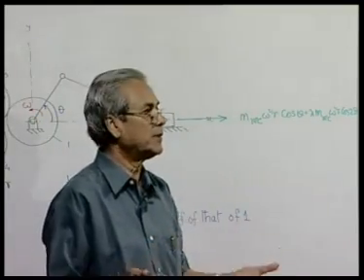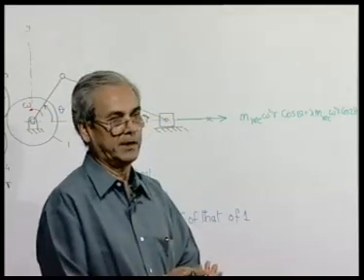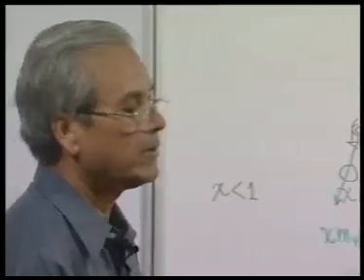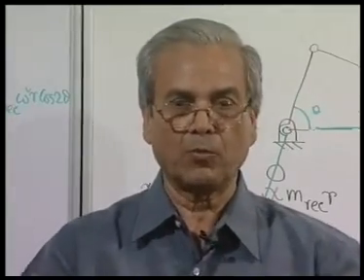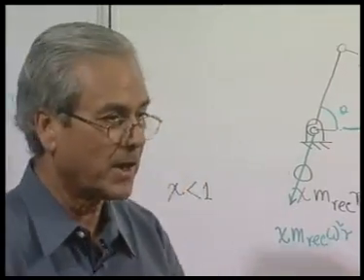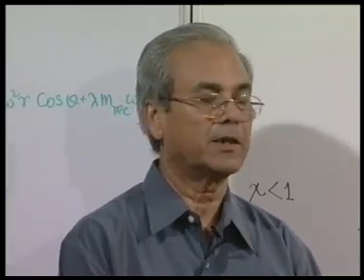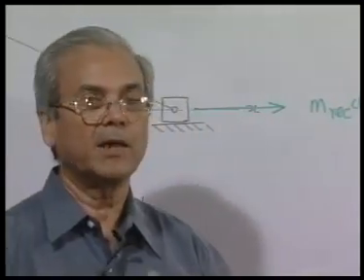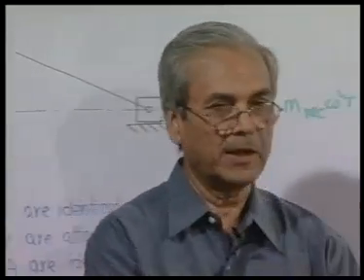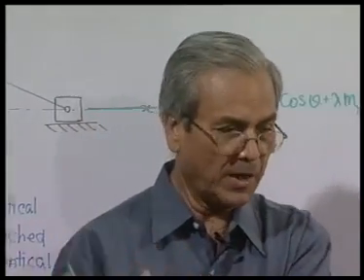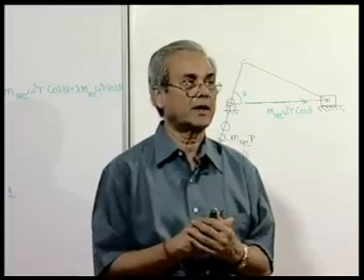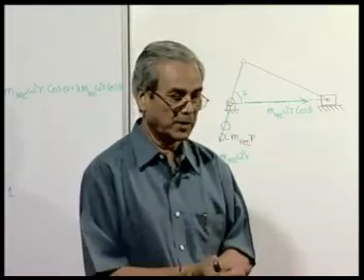That means the whole system will be self balanced, and that is why you will find that in engines where you have more than one engine, or compressors where you have more than one cylinder, this technique is employed, where the unbalanced forces of the various cylinders or engine parts will be balancing among themselves, and this we will take up in our subsequent discussions.